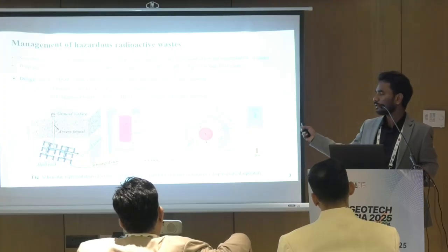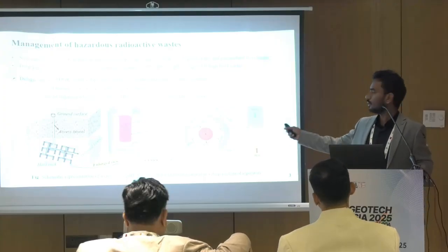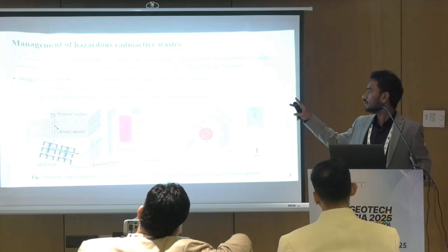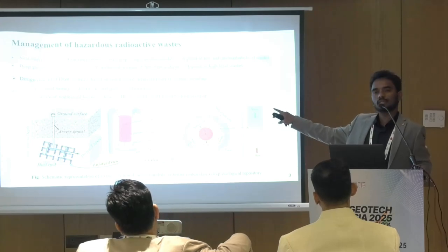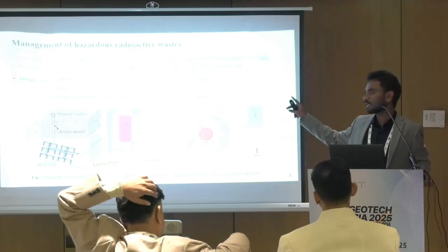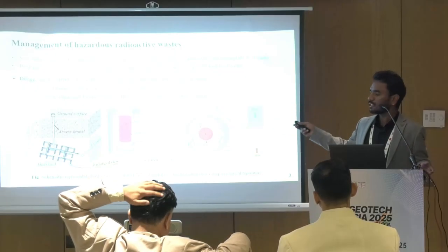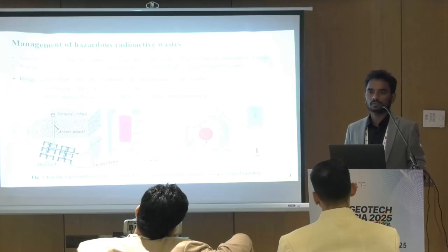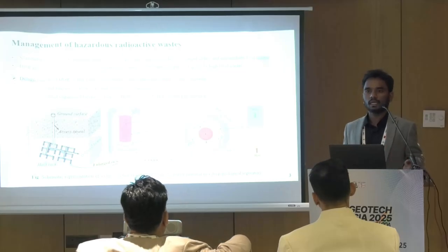If you look at the field conditions, from one end the water is coming inside, and from the center the heat is coming, generated from the radioactive waste. In these two conditions, how is the bentonite behaving? Some part is saturated, some part is unsaturated, and some part is completely dry. We need to study that condition. As a geotechnical engineer, I am not dealing with any radioactive waste. We are not going to touch any radioactive waste in the laboratory. In place of radioactive waste, we are just giving heat.